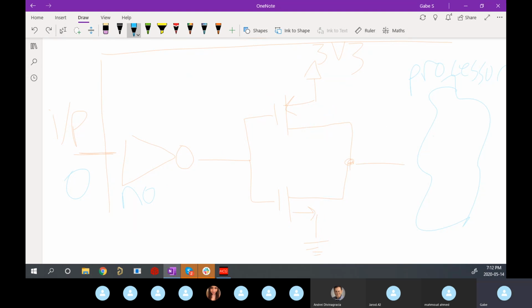Let's say I have an input 1, right? Same story. Not is a 0. My top switch likes that 0. It will close and switch, connect these two paths. My bottom one will not close. And so that pin is connected to 3.3, and I get a 1. Remember, 3.3 is logic level for 1. And my processor sees the 1, which is exactly what we had on the input pin interfacing with the outside world.